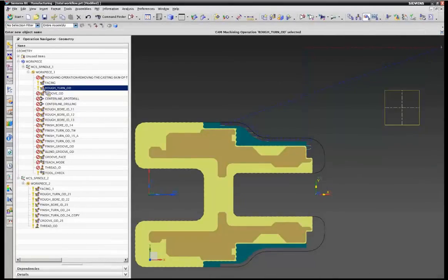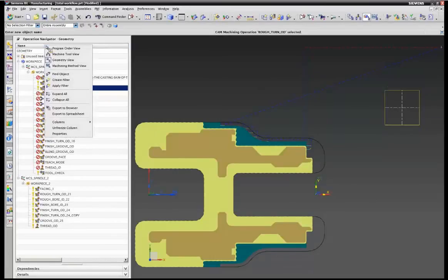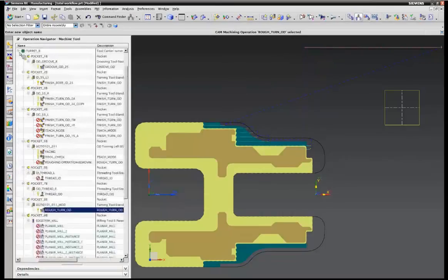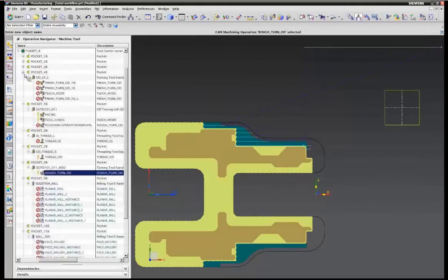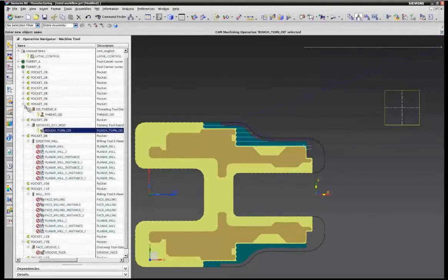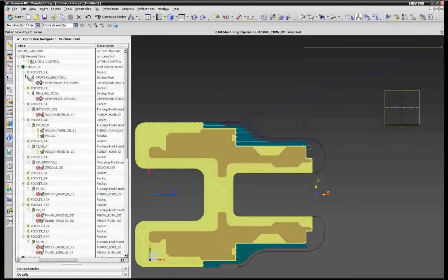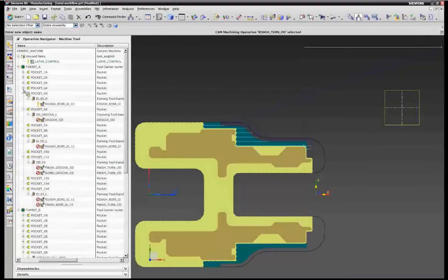Within the definition of NC operations, one of the important steps is selecting and adding your tools. And specifically for turning, one of the issues you have most of the time is the capacity of the tools in your turrets. In a turret, normally every pocket just has room for one, or maybe, if you have added devices, two tools.